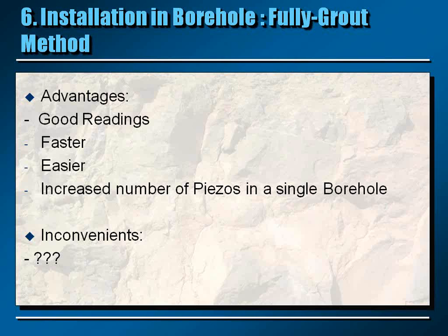There might be some problems coming from the fact that the Fully-Grout method increases a little bit the time lag of the piezometer. We would talk about maybe 10 or 12 minutes of increase. So normally this additional time lag is not so significant for traditional applications. But for some applications, like pumping tests, it might be more of a problem. So people still need to make some tests with this new method and gather more information.